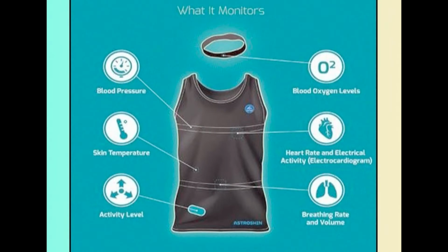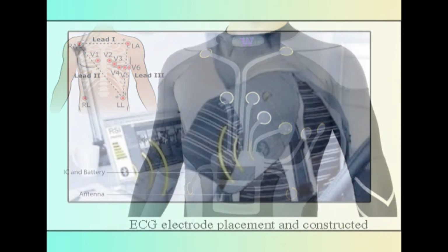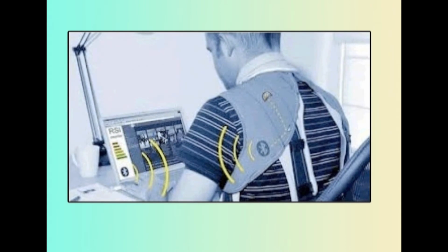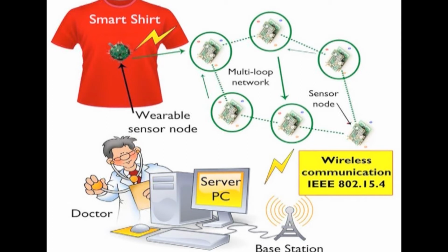piezo-resistive yarn-based fabric, with electrodes realized with metal-based yarns. A sensorized vest including fully woven textile sensors for ECG and respiratory frequency detection and a portable electronic board for motion assessment, signal pre-processing and Bluetooth connection for data transmission. A wearable sensorized garment that measures human heart rhythm and respiration using a 3-lead ECG shirt. The conductive fiber grid and the sensors are fully integrated, which means knitted into the garment of the smart shirt.